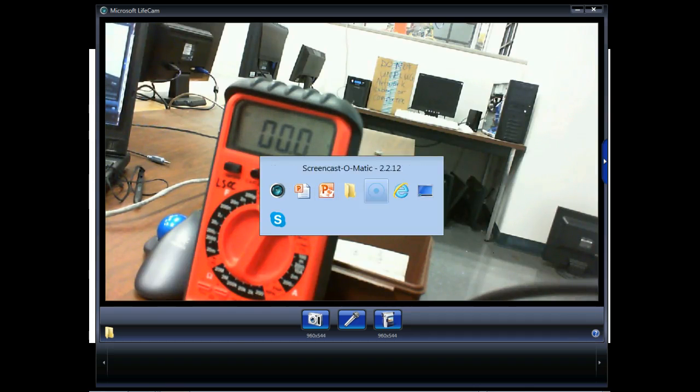So what's the average DC value of a cycle? 0. But in AC, the negative alternation does just as much work as the positive alternation. So there is not 0 volts there. There's 0 DC, right? You understand that? But there's a lot of AC. Now follow this so far.